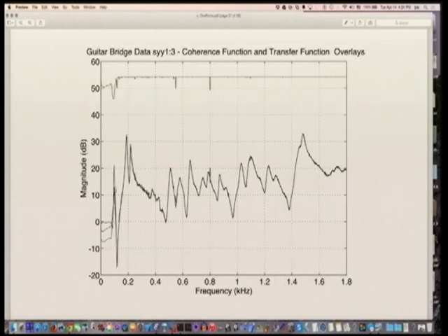You do also see that the Helmholtz resonance is the skinniest peak. That means it rings the longest. That's the longest ringing peak because it's the thinnest. The decay time is proportional to 1 over the width of these things, right? And all these other peaks are significantly broader, and you can see a progressive widening of the peaks as you go up in frequency. That means in the time domain there's a progressively faster decay as you go up in frequency. So the modes are decaying faster at higher frequencies, and this is something you see all the time. It's very typical of physical systems. You get more damping at higher frequencies.